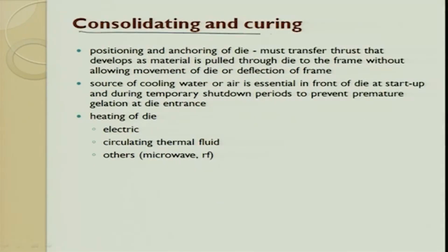So, consolidation and curing, the positioning and anchoring of the die is very important, must transfer thrust that develops as material is pulled through the die to the frame without allowing movement of the die or deflection from the frame. So, this is very important. I repeat, it must transfer thrust that develops as material is pulled through the die to the frame without allowing movement of the die or deflection of the frame.